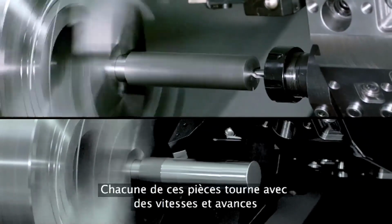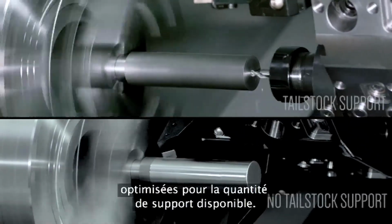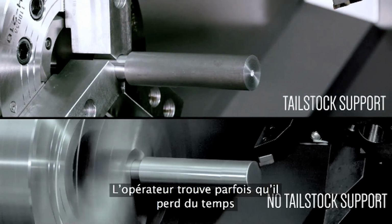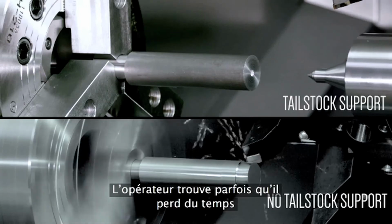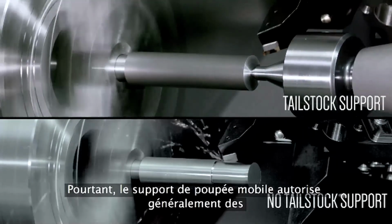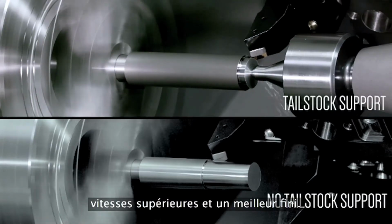Each of these parts are running with speeds and feeds optimized for the amount of support available. Machinists sometimes worry that they'll lose time waiting for the tailstock to clamp their part, but tailstock support usually allows higher speeds and better finishes.